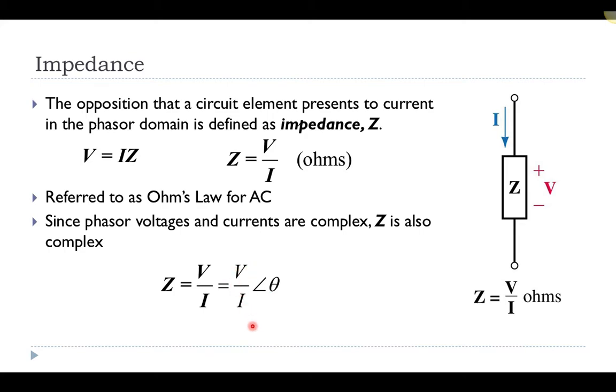with the phase angle between these two components. So over here I have a picture. I have some box that contains something. It could be a resistor and an inductor. It could be just a resistor. It could be an inductor and a capacitor. There are components inside here that have some overall impedance. There's some current that's entering those components. There's some voltage that's developed across them. This voltage and this current may not be in phase with one another, and in fact the phase difference is an angle theta, so that the voltage in this picture right here leads the current by an angle theta.